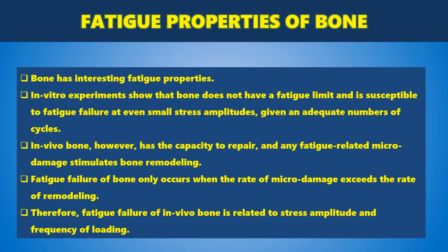Let's have a look at fatigue properties of bone. Bone has interesting fatigue properties. In vitro experiments show that bone does not have a fatigue limit and is susceptible to fatigue failure at even small stress amplitudes, given an adequate number of cycles. In vivo, bone, however, has the capacity to repair, and any fatigue-related microdamage stimulates bone remodeling. Fatigue failure of bone only occurs when the rate of microdamage exceeds the rate of remodeling, as we can see in stress fractures like the metatarsal fractures in soldier recruits.